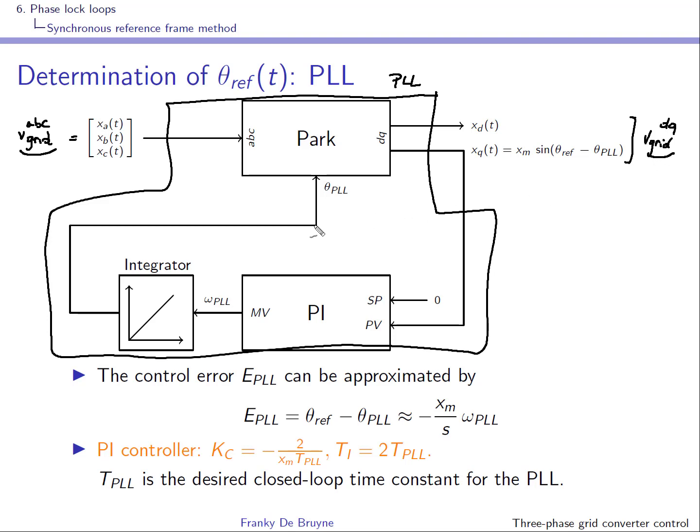And what I will have at the output also is the reference angle. I will call it reference angle, because once my PLL extracts the reference angle, what I will observe over here is really the reference angle. So the output of the block in the next slide is indeed the reference angle, and what I can output also is the speed omega ref.